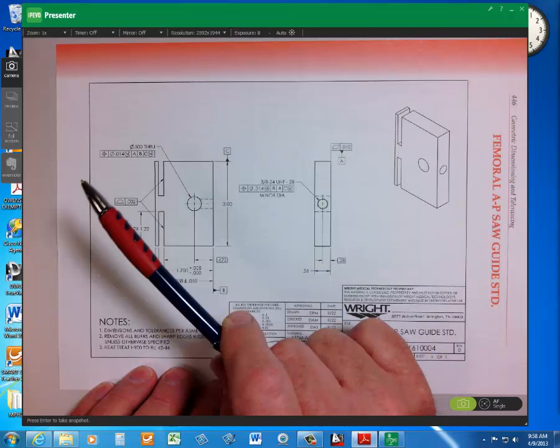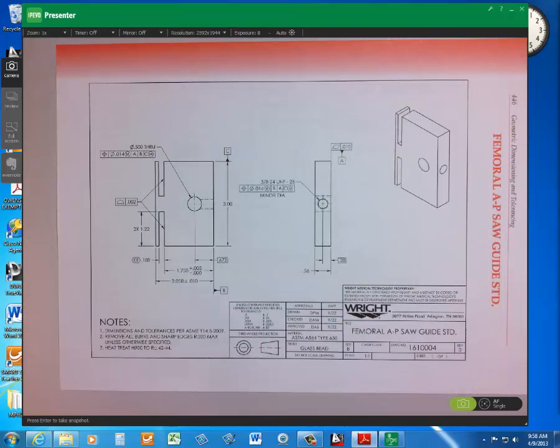And then at the half-inch, or 0.500 produced size, your position tolerance would be 0.019. Your virtual condition would be 0.481. Your produced size at 0.495, your position tolerance would be 14 thousandths. Okay, hole at its smallest. Your virtual condition is 0.481.